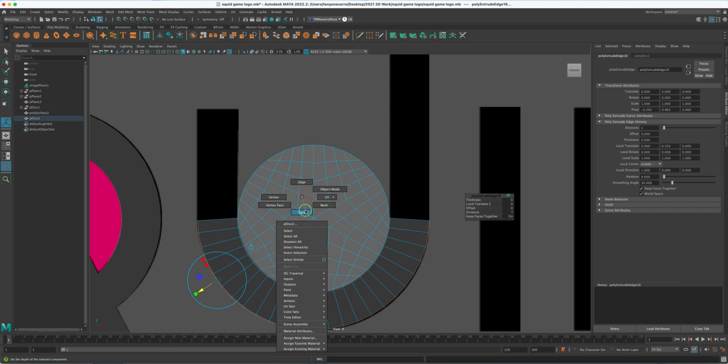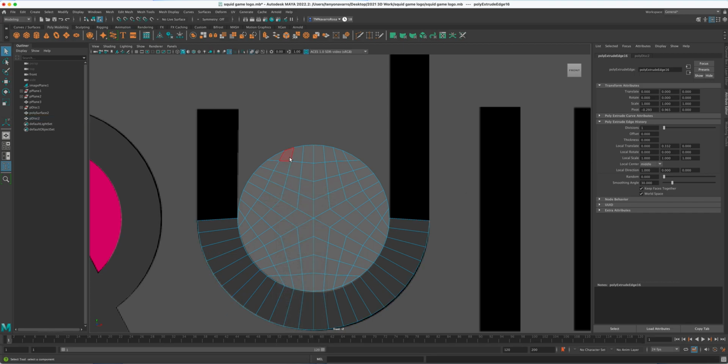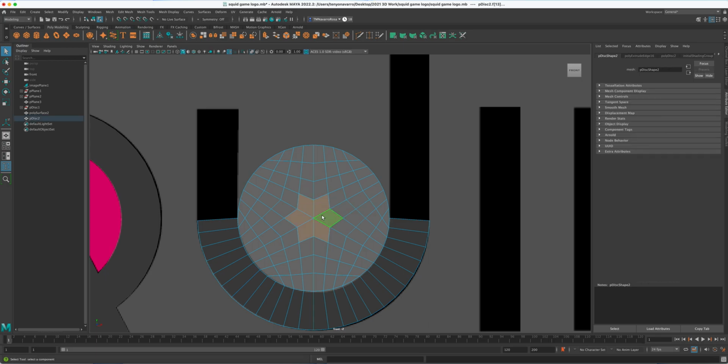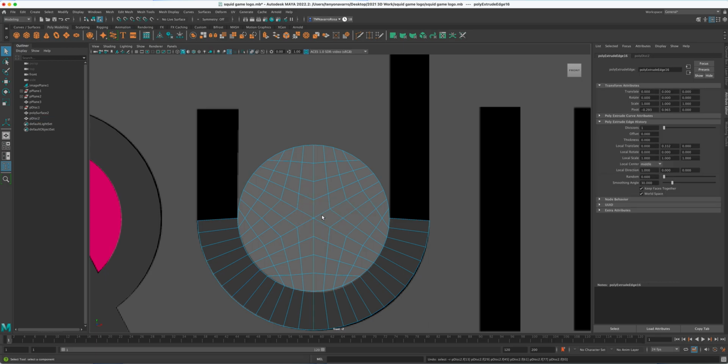So how do we do this again? We can select the faces in here. Let's select the faces. So, it's another way to do this, guys. So let's say you don't want to select faces and you want to get this done fast. There's a paint selection, but we can use it for this also. If this is too big, you hold down B, right middle click, and you drag, and we get a smaller brush.